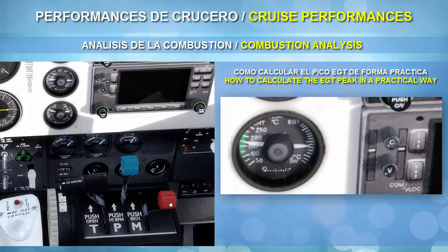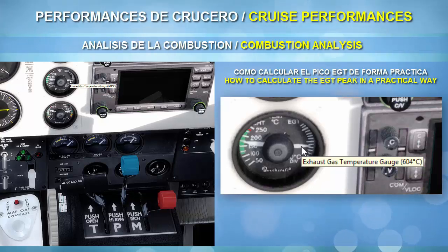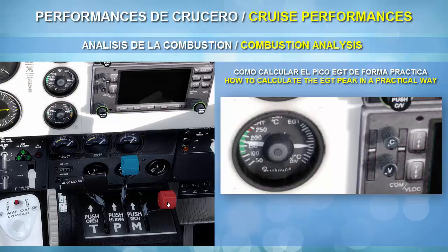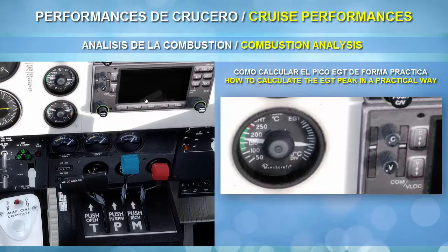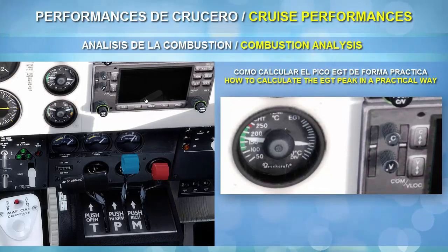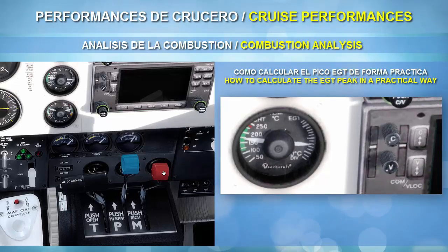It's not absolutely necessary that the mixture be extremely accurate with total mathematical precision, okay? More or less, more or less. Don't worry about that, okay? But that is the idea. And in that way, right now, you know, or you should know, how to understand the cruise performance tables, okay? I will enrich the mixture a lot because I will put the red lever forward again, and we will calculate the EGT peak again, okay?